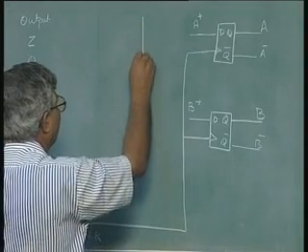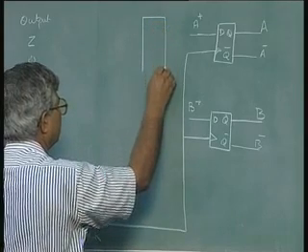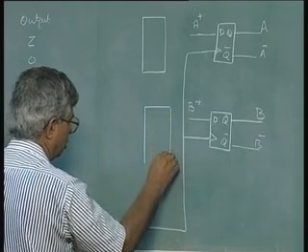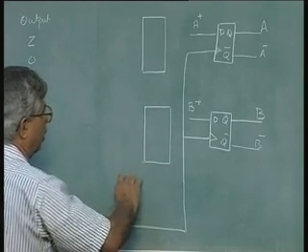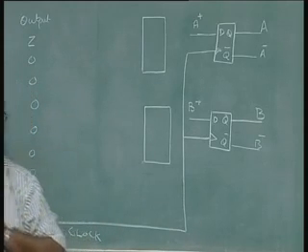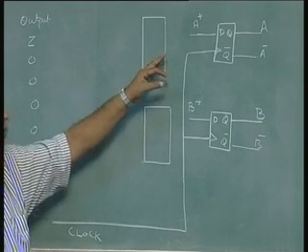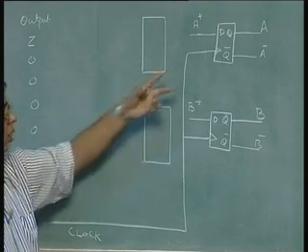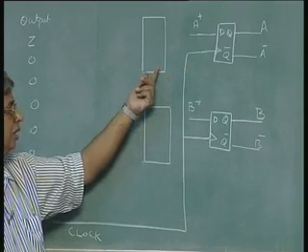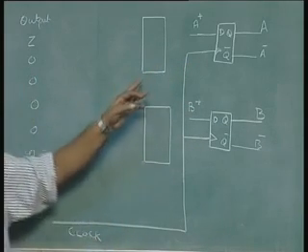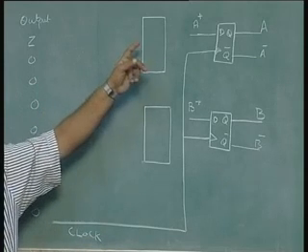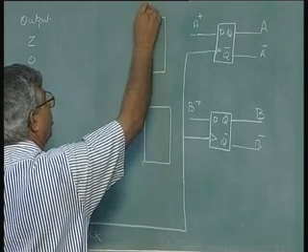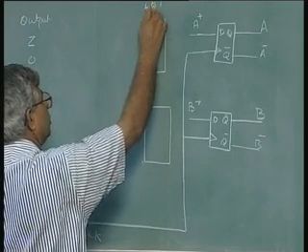In this case, I am going to make multiplexers give that input. So, what I am going to do is to put a multiplexer here, another multiplexer here. And what is the size of the multiplexer? The size of the multiplexer is decided by the number of different inputs it will have. Now, there are going to be 2 state variables, that means there are going to be 4 combinations of inputs. For each combination we should decide the next state. So, if you have a 4 to 1 multiplexer here with 2 control lines,